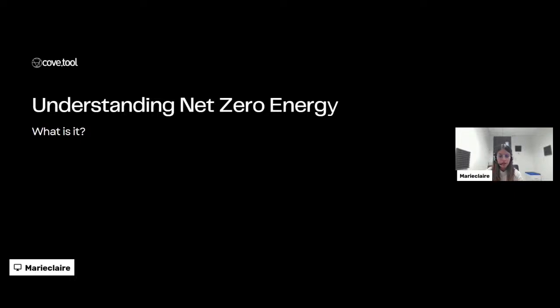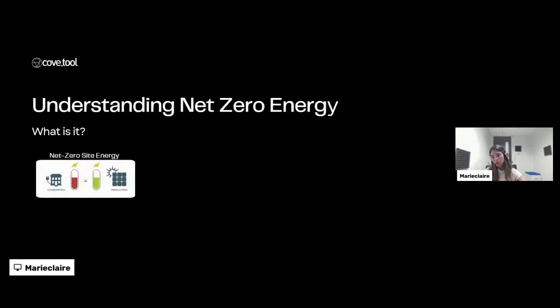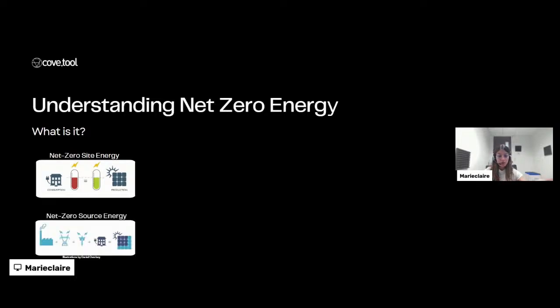To start with our biggest topic today, I think that we need to first understand what it is. I bring four main definitions by the National Renewable Energy Laboratory, which is the prime authority on this topic. First, we need to understand what net zero site energy is. It is just a building that produces as much energy as it consumes on an annual basis. Then we have source energy, because over 60% is lost in generation and delivery. To be net zero source energy, we need to produce 100% of the energy used to generate and deliver from the power plant to the site, plus that site energy that I just defined.